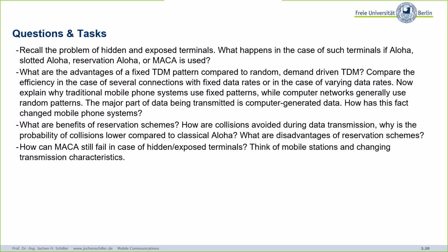For example, when we set up a wireless network in our building using more than 400 nodes for sensor networks, we experienced that more than 70% of the connections were only unidirectional. That means only one device could send to another, but not the other way around.